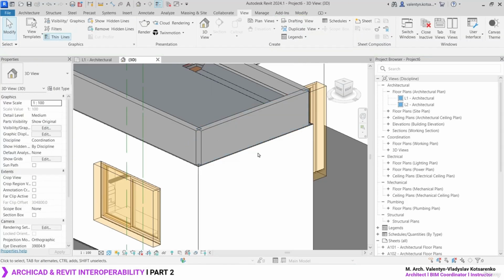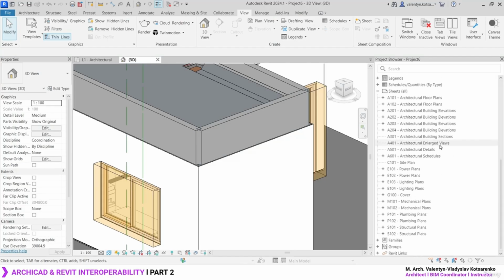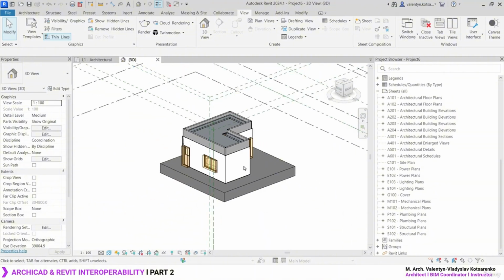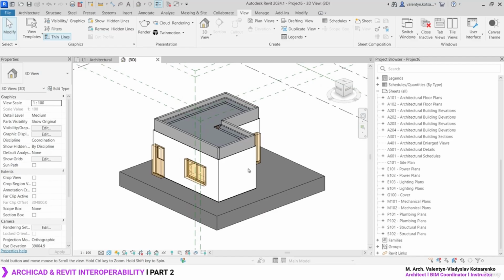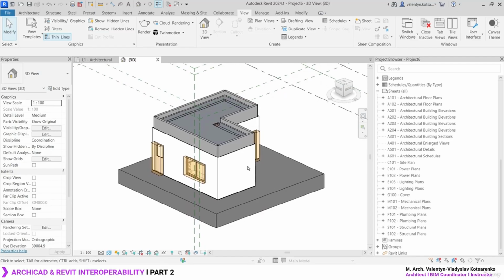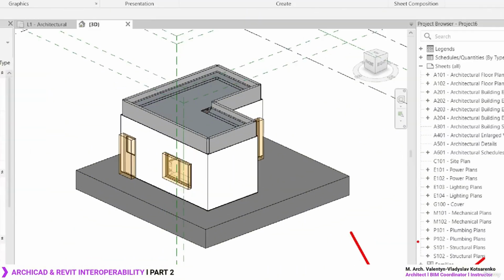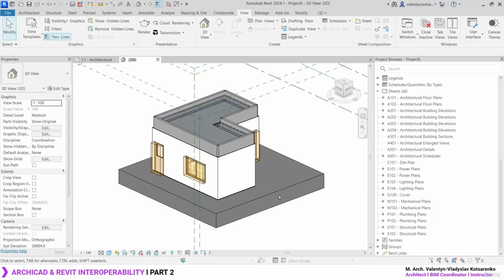So that's a bummer. You can always export from ArchiCAD to Revit, but everything will behave as a direct shape, intended for reference models or for quantity take-off. But if you're planning to continue editing the model in Revit, it's not going to be an amazing idea. It's still possible with a lot of effort, but I highly suggest that you never export if you're intending to continue editing the model in another BIM platform. If it's for editing purposes, the best thing is to always start from scratch in one BIM platform or the other: either use ArchiCAD from scratch or use Revit from scratch.